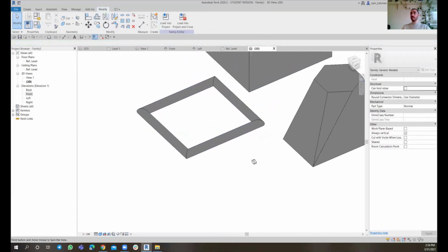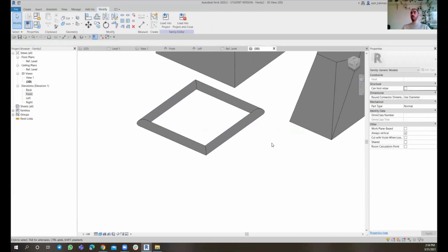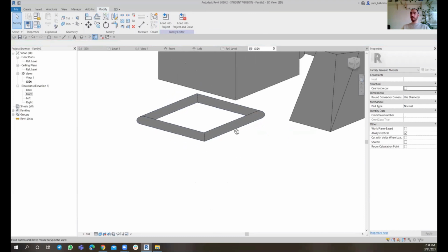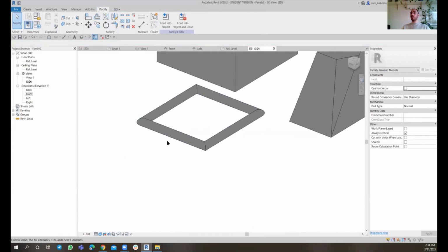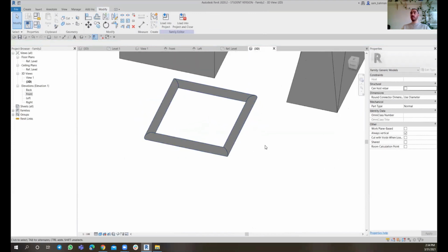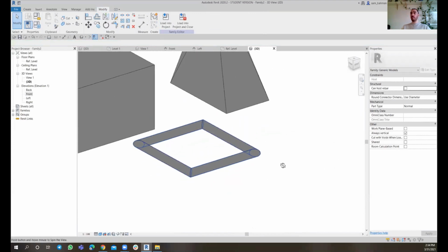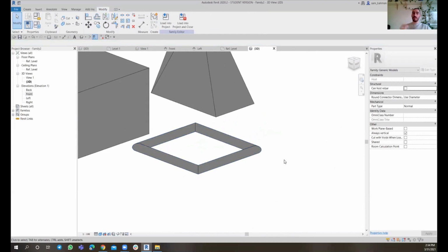Now, once I click on finish and do a final finish again, as you can see, a sweep model just getting happen. So I would say most likely with sweep, you would be able to define frames, right? So frames are usually formed with the sweep. Sweep is like very useful and very common in, I would say, almost every single component or family that you wish to create. So that is sweep.